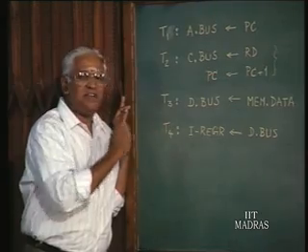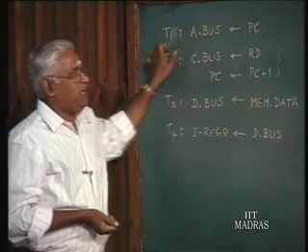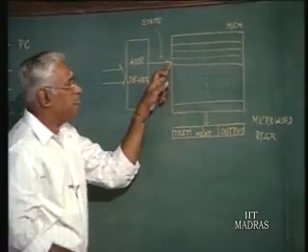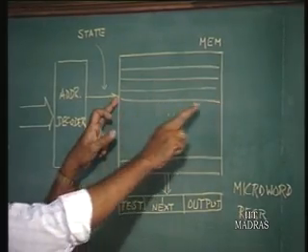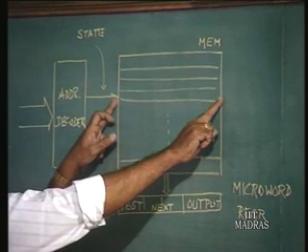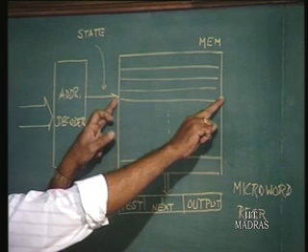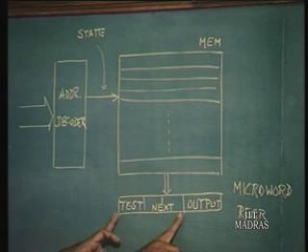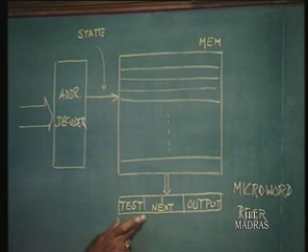We were seeing the data path in the previous lecture, and then I said that for one state, the code which we had arrived at can be put in the memory, then one word in the memory will contain information about that data path control. And then I also showed with reference to the ASM chart, showing the T1, T2, T3 and T4 states, how other fields in the particular word must also be added in addition to the control, namely next state and then some inputs which must be tested in each state.